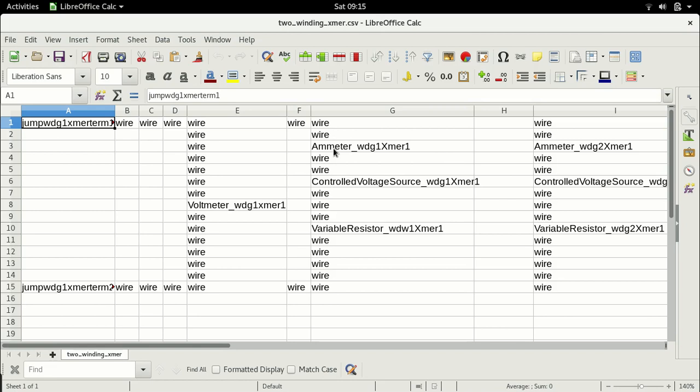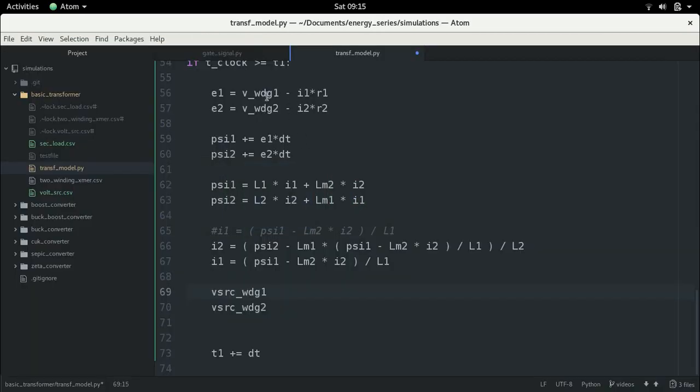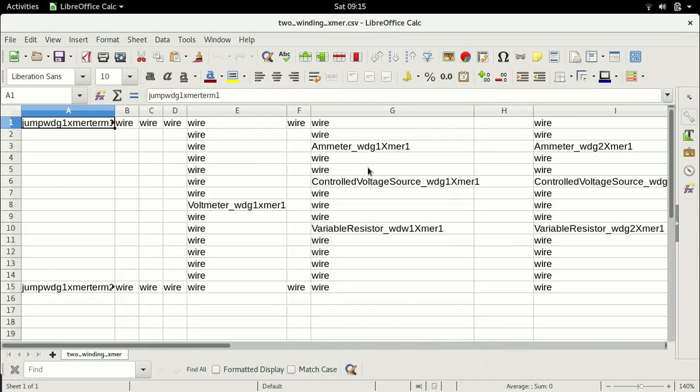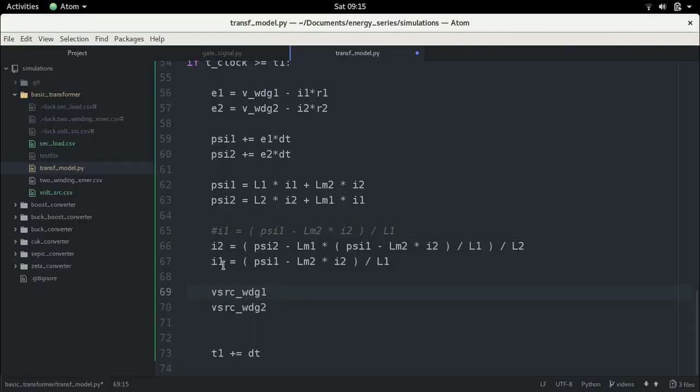This is just simple Kirchhoff's voltage law. If you have a doubt, just go and draw the circuit and write this equation yourself. It's just simple Kirchhoff's voltage law, where V minus IR is equal to E. And for that to happen, this current has to be flowing downwards. Now, if the current has to be flowing downwards, this controllable voltage source will have to be equal to the induced EMF, right? Let's take a look at this. For example, we have already calculated the current.